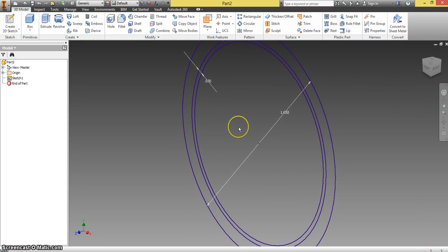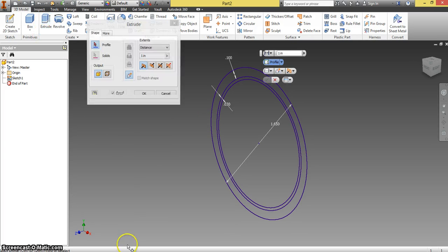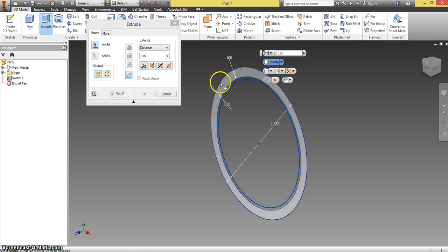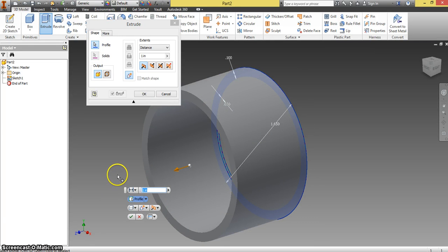Finish sketch, double click my scroll so everything comes on the screen. I am going to extrude. We've done extruding a lot. But for right now, I believe I am only going to extrude this outer shape, because right now I am just going to extrude the tire part of that. I'm not going to extrude any of those little ribs that are in there or anything. So right now, notice profile is shaded. I'm selecting the profile I want to extrude.